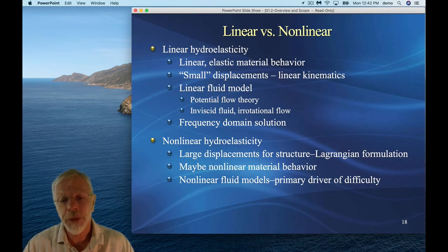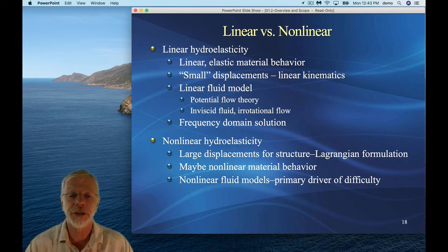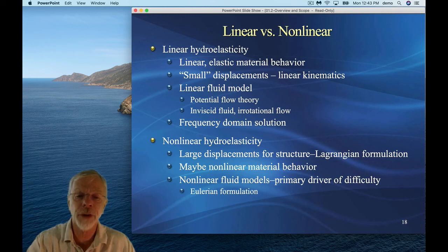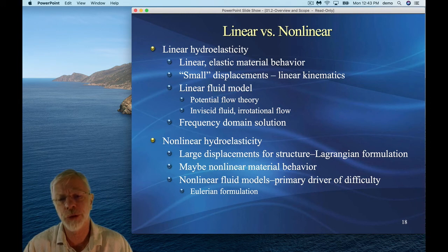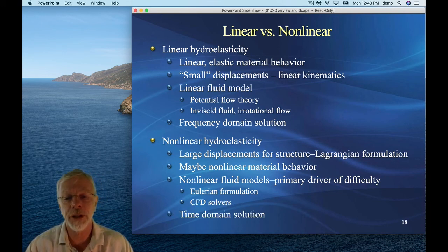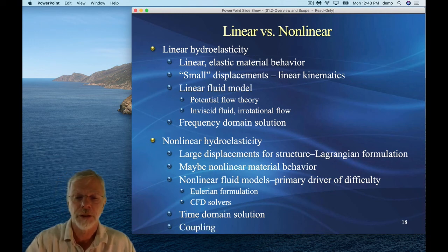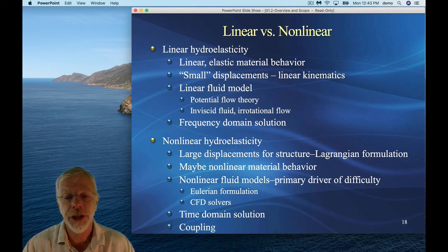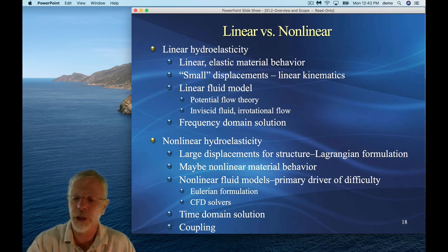And then typically, what usually drives the requirement for nonlinear hydroelasticity is we need a nonlinear fluid model. And there we typically use an Eulerian formulation. So we're typically using a Lagrangian formulation for the structure and an Eulerian formulation for the fluid. CFD solvers are typically used for this. And of course, then it's got to be in the time domain. The big challenge there is the coupling between the Lagrangian structural mesh and the Eulerian fluid mesh.